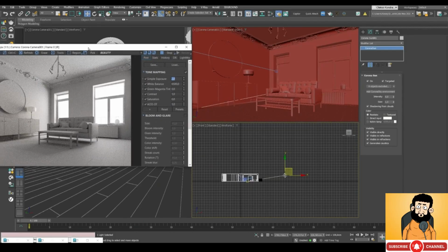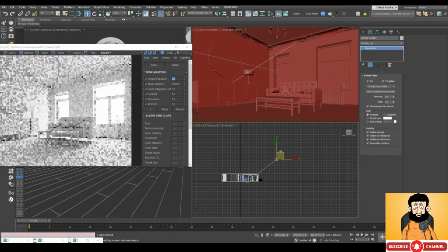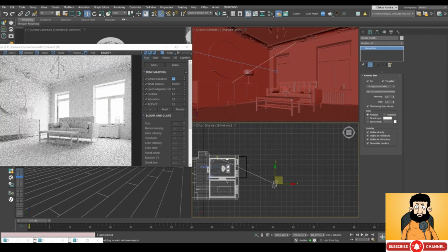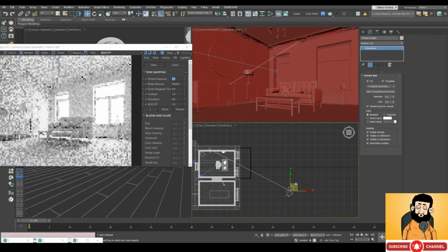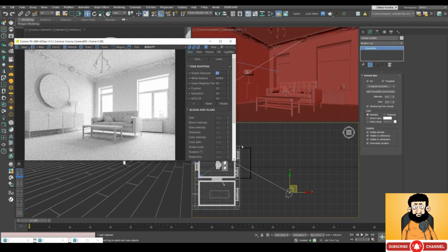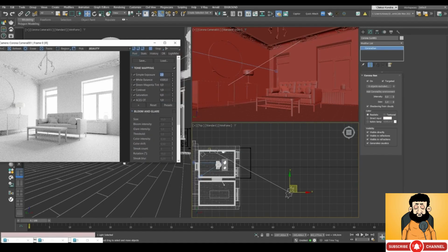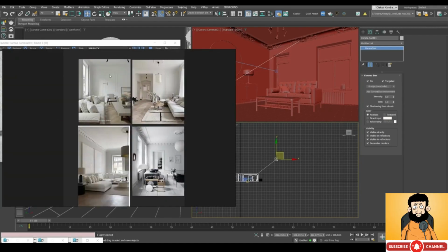Alright, so summing up, to create basic daylight when the sun is shining through the windows, but not too bright, you can use the sun-sky model. So you basically tie in the sun and the sky, and you direct the sunlight onto the wall opposite to the camera, between the windows. Let's try to imitate lighting in these references.